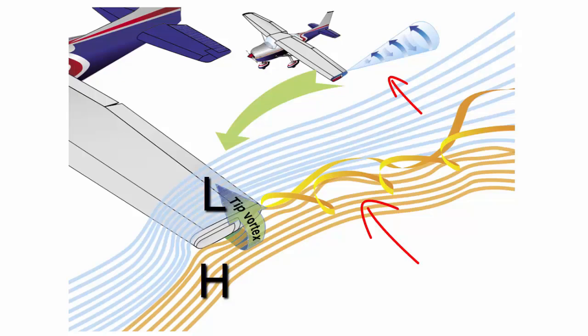Airplane manufacturers have developed different methods to counteract this action. Winglets can be added to the tip of an airfoil to reduce this flow. The winglets act as a dam, preventing the vortex from forming. Winglets can be on the top or bottom of the airfoil. Another method of countering the flow is to taper the airfoil tip, reducing the pressure differential and smoothing the airflow around the tip.